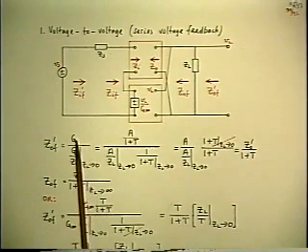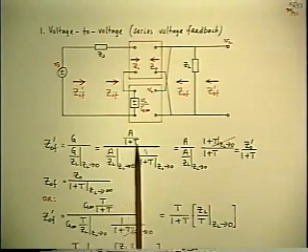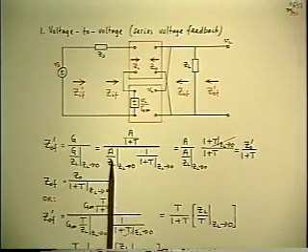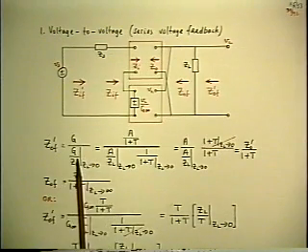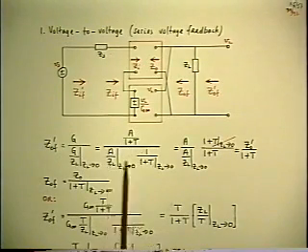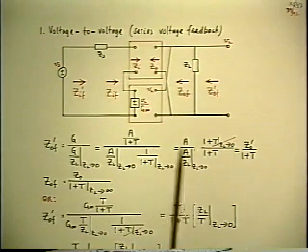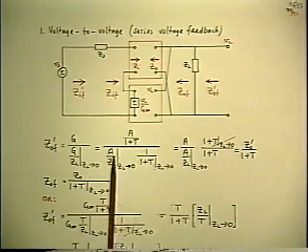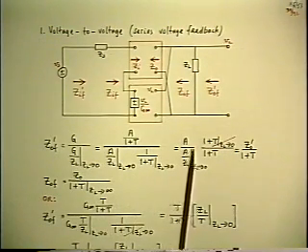All you have to do is substitute the known relationship for the G in terms of the open loop quantities. So you could substitute A over 1 plus T in both places. But you can take the limit factor by factor. So G has two factors, A and 1 plus T. I've separated the two factors, and you can take the limit independently. Then I've collected together the A from the numerator and the A over ZL with the limit from the denominator, and put that out front.